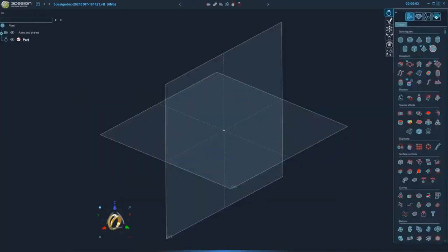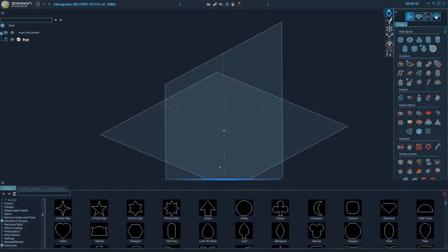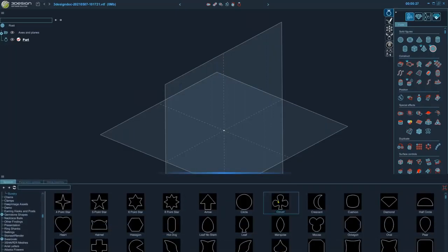Okay, next up we have super bulge. With super bulge, when you get into bulge on complex shapes, you have to know a little bit about surface controls and deleting the surface and playing around with the settings and hope that it all matches up and welds back together. So basically, we've done all of those more complicated steps into a new version of bulge.